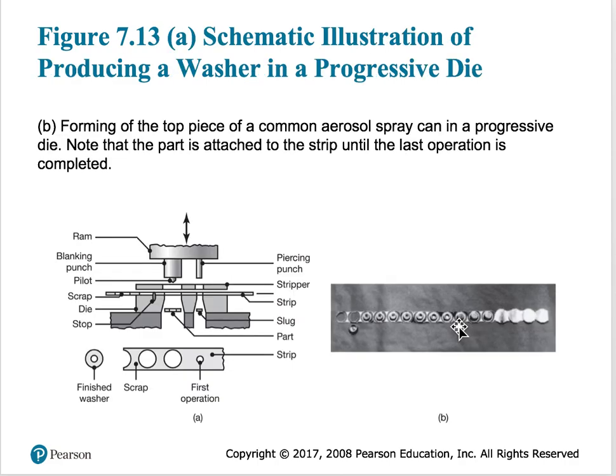So you are not going to have one single die or one single stroke to create that. It is not a simple punch and die process, so you have to do it in multiple steps. And they are slow, and these dies are also pretty expensive for individual shearing operations.